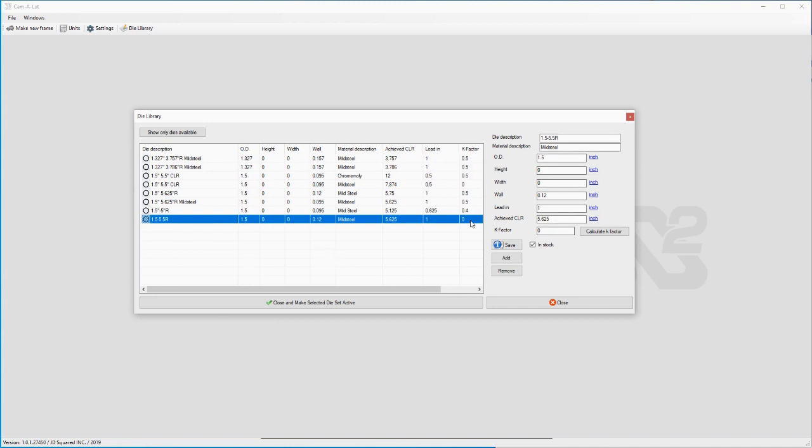Well, that centerline radius of the part of the tubing that did not compress or stretch is called a K factor, and it's a percentage of where on the workpiece it is. So 0.5, like this one right here, would mean that the thing didn't grow or shrink in length because the K factor was right in the middle. So when you bend it, it stayed in the middle. That's never the case. It's always going to stretch a little bit when you're bending tubing or pipe.